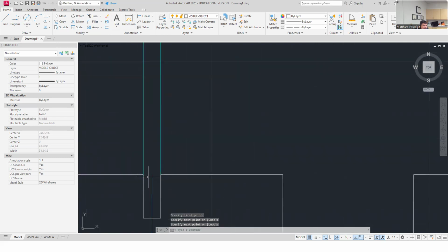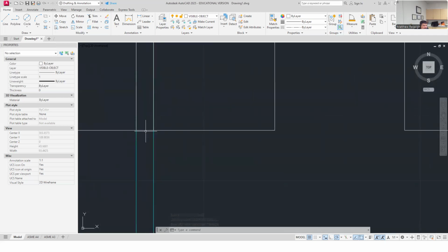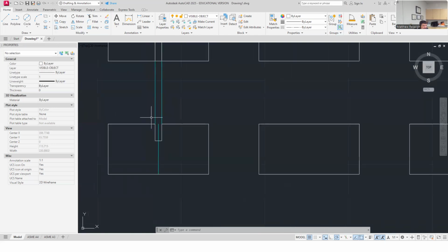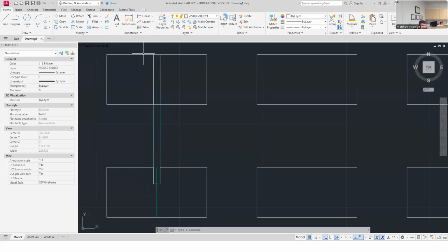I did have to trim that out too because that visible line doesn't exist anymore. It is here though, right? I don't think that gets cut here because, technically, this surface right here, while it's cut through, and I can see that it's visibly cut from the front view. From the top view, I should still see the side come through there because I've still got a bunch of surface that's in alignment with this,